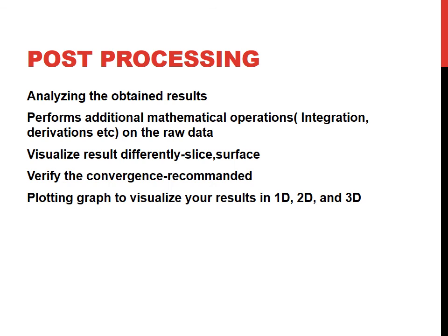Another thing is we can visualize the results differently by performing a slice or visualization on the surface, and we can also plot the results to get a graph in either 1D, 2D or 3D. And then it's also recommended to verify the results by doing convergence calculations.